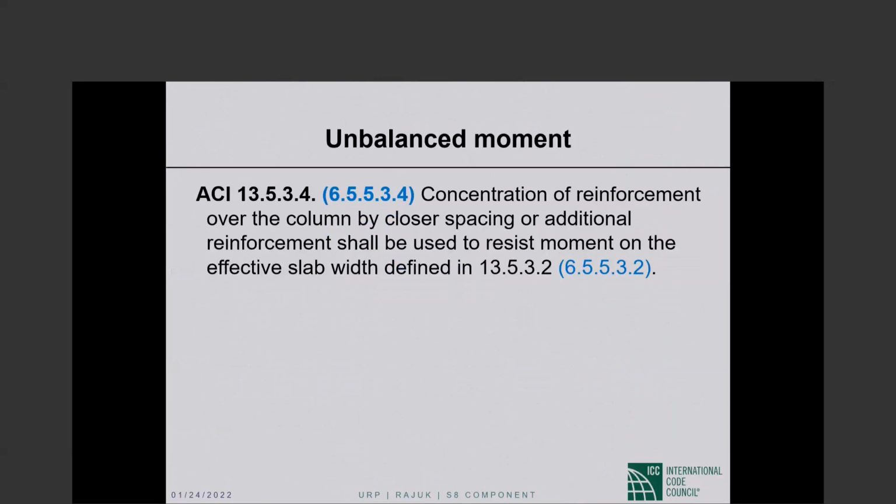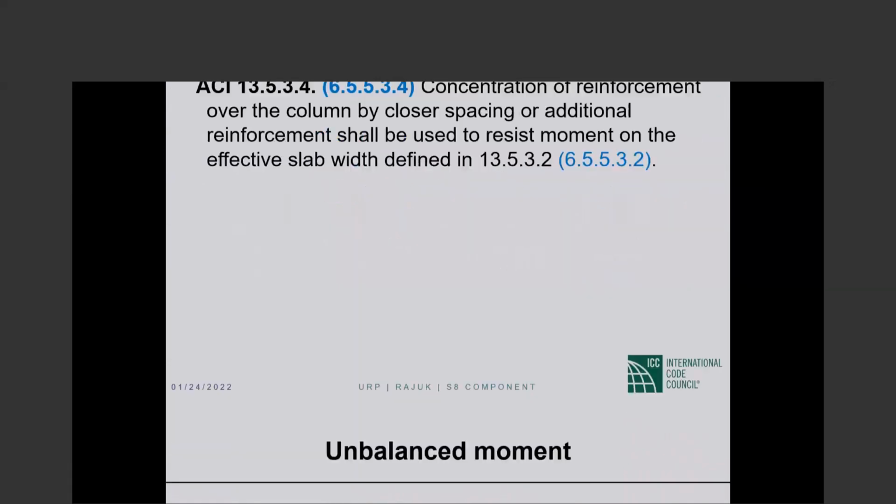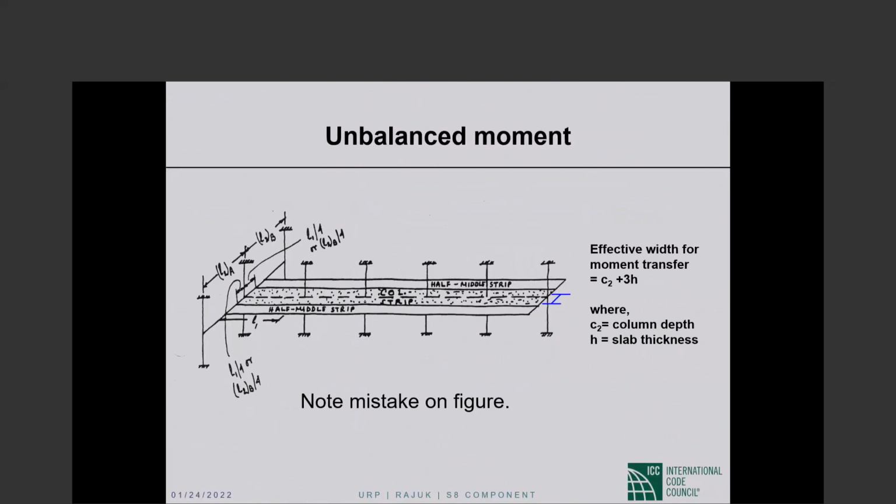Concentration of reinforcement over the column by closer spacing or additional reinforcement shall be used to resist moment on the effective slab width defined in such and such. Okay, let us go there. This effective slab width that they're talking about, and this concentration of reinforcement and so forth. This is something you absolutely got to understand.